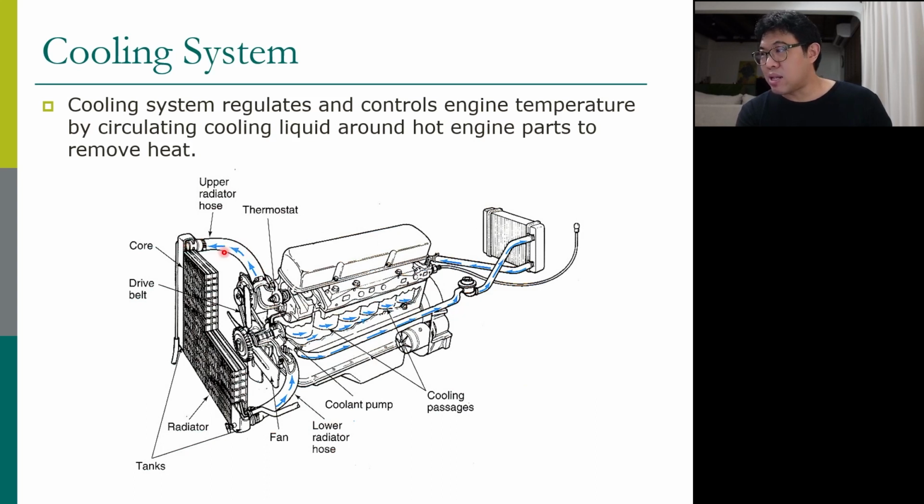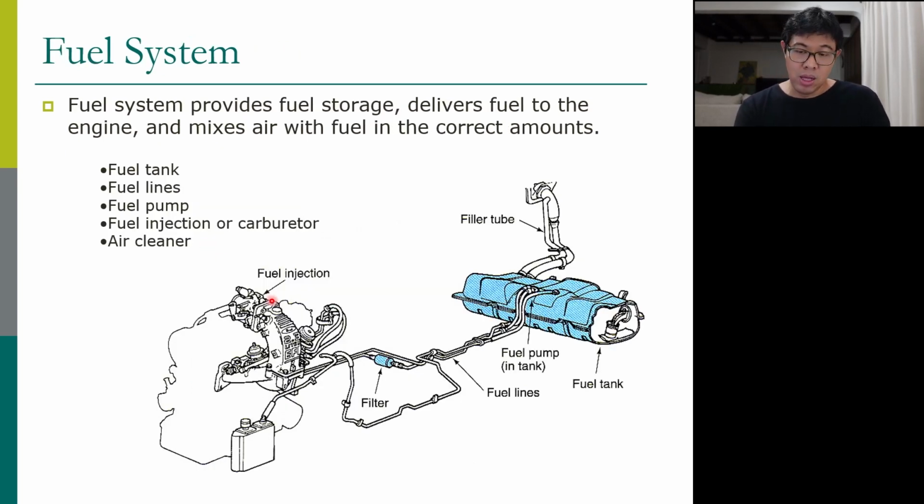Then the heat in the water coolant is removed inside this radiator, to the air that is coming in from the front. So the air comes to this radiator and removes heat from the coolant, and then the hot coolant becomes cold coolant here, and that cold coolant goes into the engine, picks up heat, and goes out to the radiator just like that.